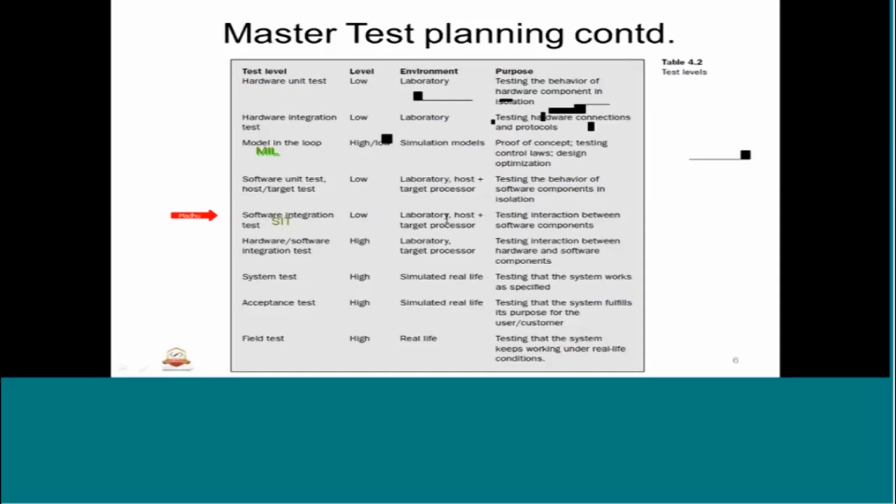It's also low level. It is done with the help of the target port connected to the host. We know how the target is interfaced with the IDE, then the debugging environment, breakpoints, and all that. We will use it to do the integration. Basically, here we try to integrate the different software pieces within the system. We will pass the parameters and test against those parameters whether the intended behavior of the flow, be it control flow or data flow, is met. That will be the aim of the test.